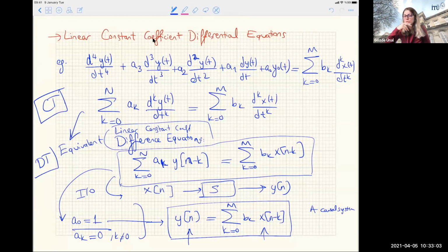If it depends on past values of the output, you have to go to, like I said, some recursive formulation. But for us, we are interested in filter coefficients that are really like windows that can be slid over our input data, and then we can calculate them efficiently by these finite impulse response systems.